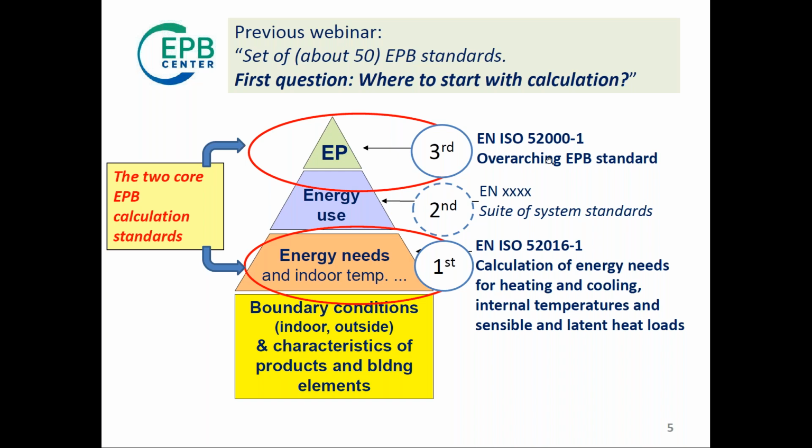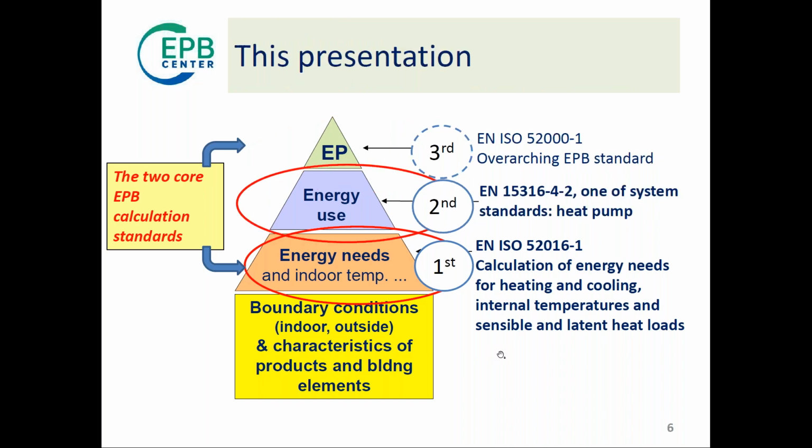This standard is about the aggregation of all the energy uses by the different systems, also energy exported to the grid if you have electricity production on site and so on, and very important, conversion of primary energy. But Laurent Sokal will explain more about this part of the calculation further on today. And so this is what I said at the previous webinar. So now at this webinar, I concentrate on the link between the energy needs calculation and one of the system standards, which is the heat pump system standard.